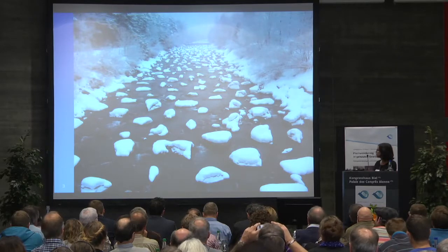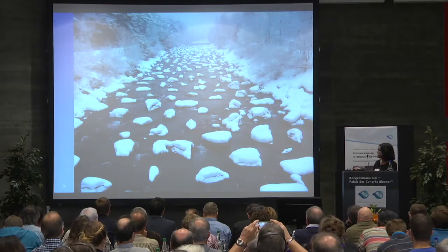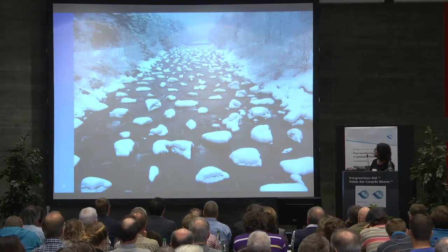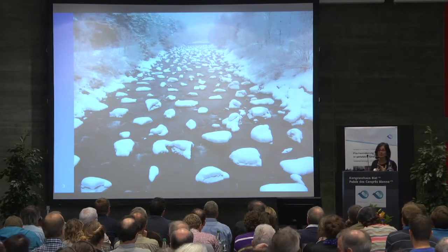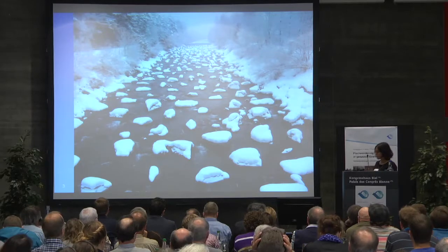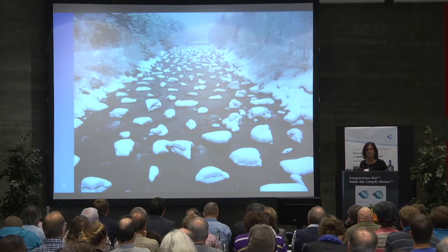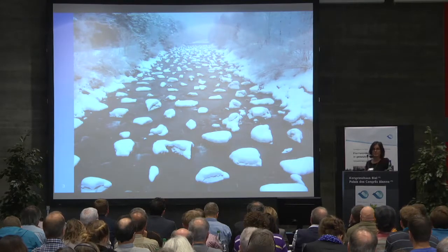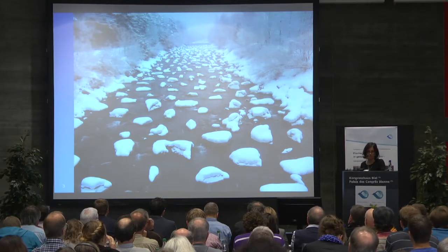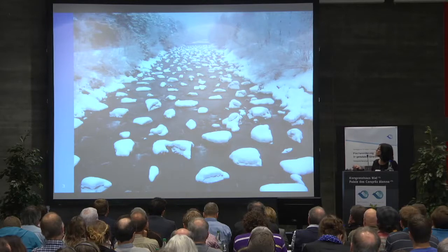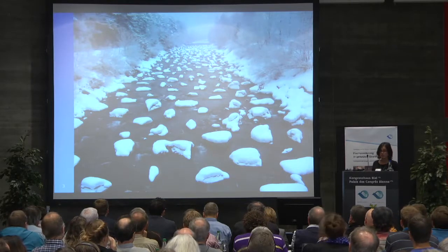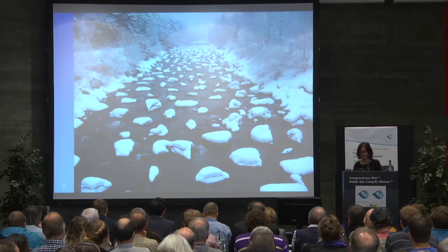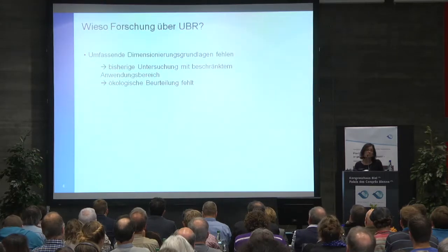They are determined by 3 parameters. That is the diameter of the individual rock, 1.4 to 2 meters. They are huge and weigh about 5 tons each. On the other hand, that's the second parameter, the sediment material, the grain composition, and the density. That is the relationship between the total surface with rocks and the total ramp surface. This is 20 to 25 meters wide. This ramp is 100 meters long, and 20% is the density.